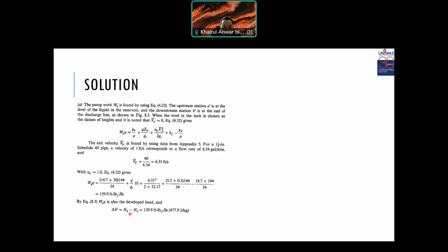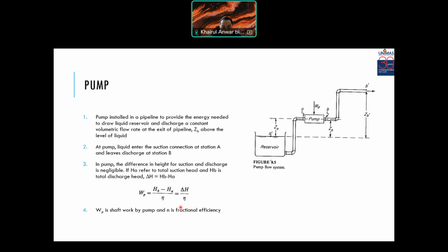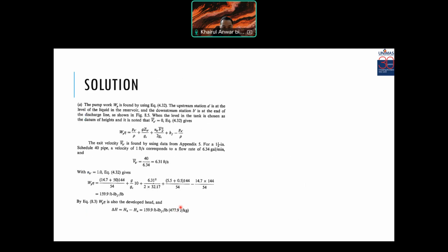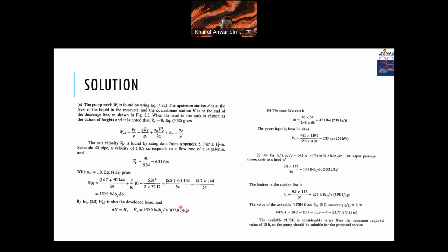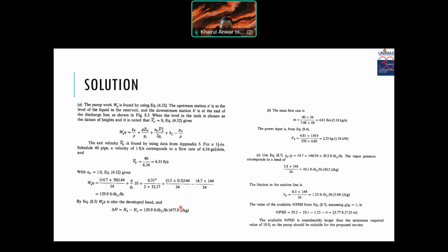So delta H equals HB minus HA, which is equal to this value. Refer to this equation. This equation is the developed head of the pump.